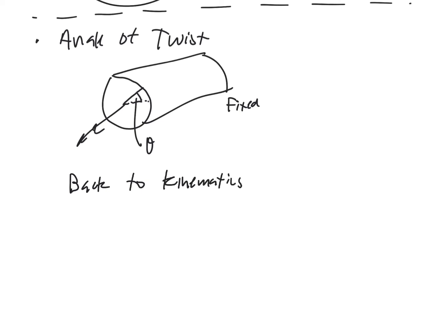And incidentally, this is kind of typical for a solid mechanics analysis. Remember, we go from displacement to strain to stress to force. In this problem for torsion, it looks like this. If I apply a torque, it twists theta. That theta leads to a shear strain. That shear strain leads to a shear stress. That shear stress gives a moment or a torque that balances the applied load.